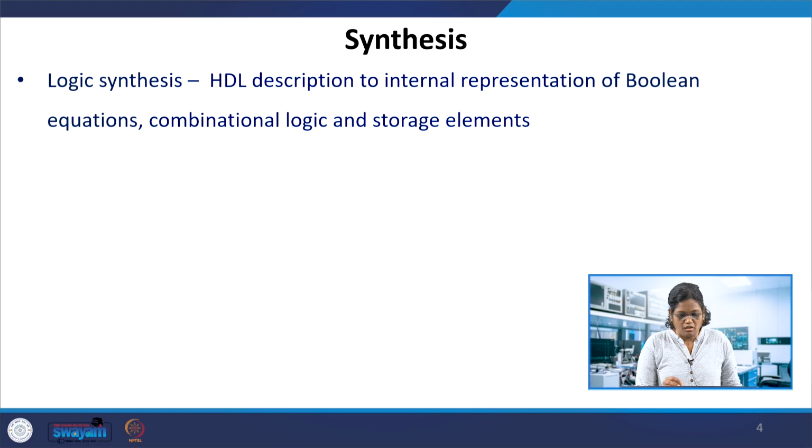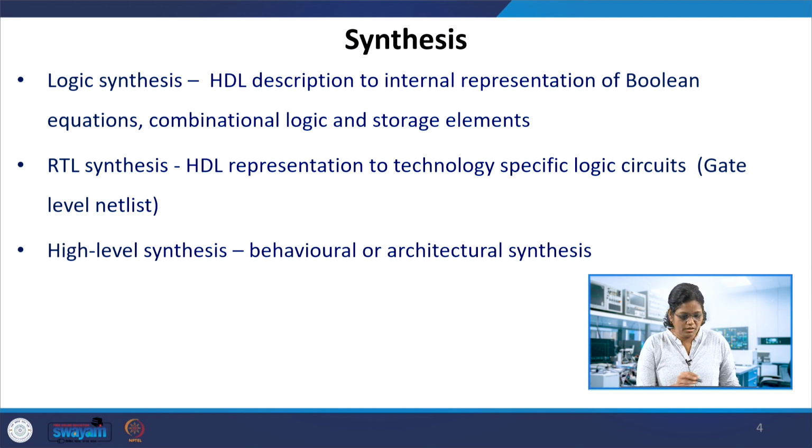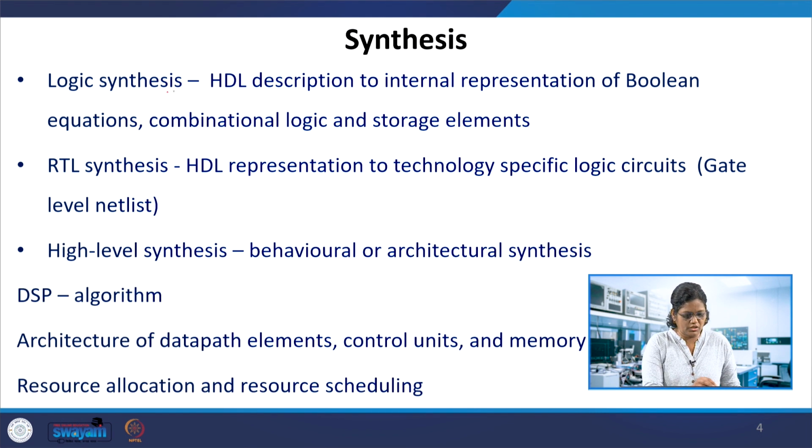And then synthesis can also be done. I mean, three types of synthesis we can have. One is logic synthesis, another is RTL synthesis, whereas the third one is high level synthesis. The logic synthesis is where the Verilog code which is written, the module, is converted into an internal representation. It can be Boolean equations, that is equivalent to combinational logic or storage elements. So the conversion from this Verilog code to this representation is the logic synthesis.